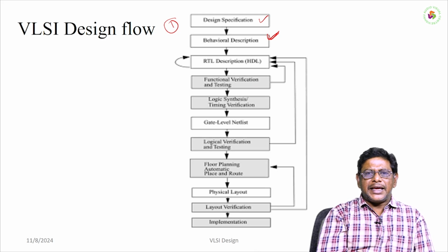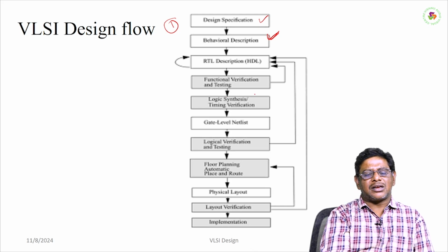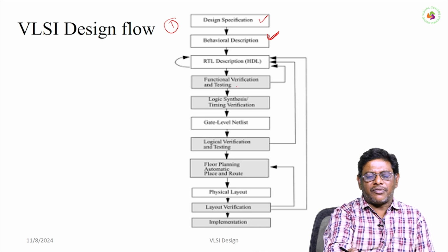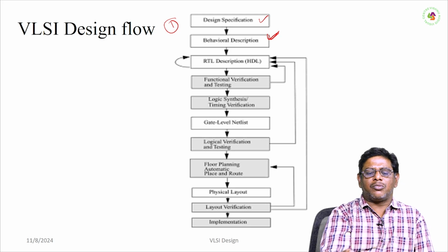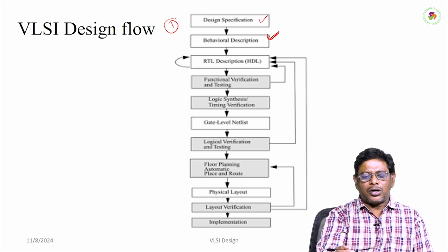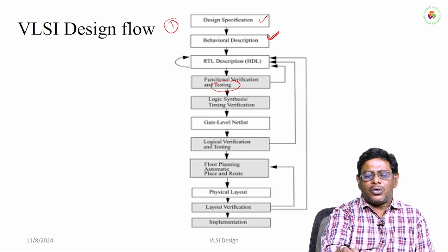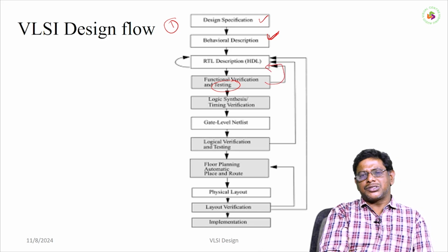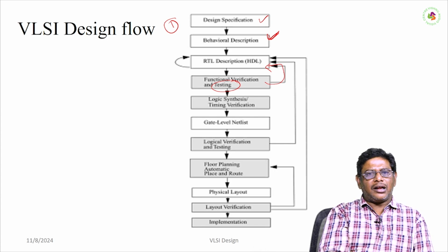Considering each functionality in the form of registers, we describe its functionality by applying different combinations of inputs. Then we go for verifying the functionality. Once it is proven, we move on to the next stage. If not, we test again and again in the same place. So we go back and consider whether we have taken the right inputs or not, and whether we have chosen the right design of the RTL or not.